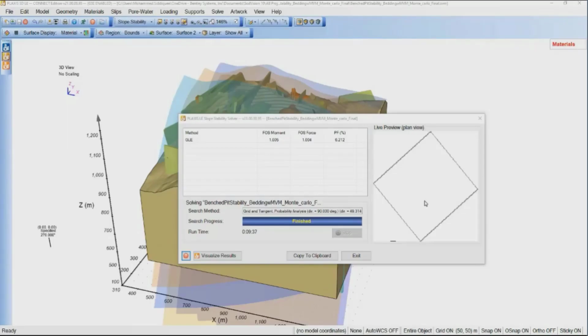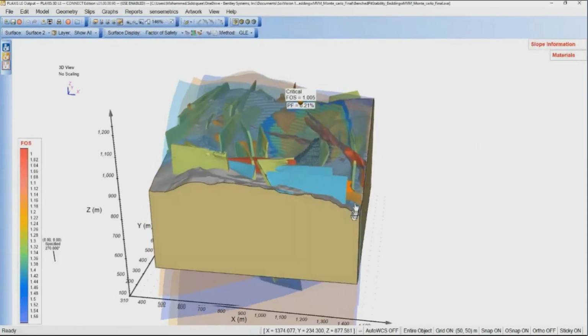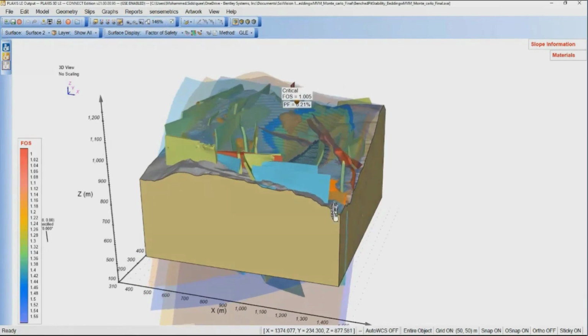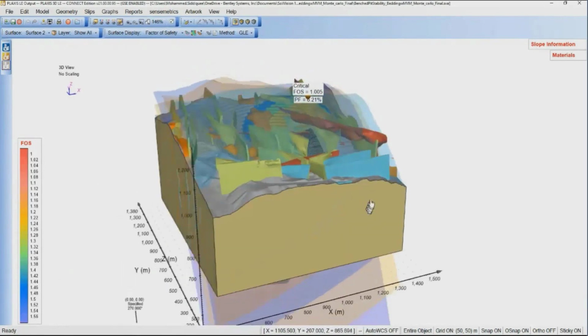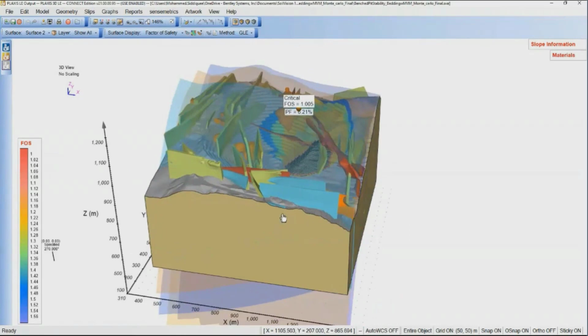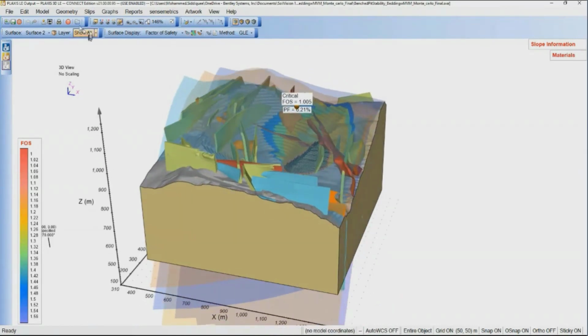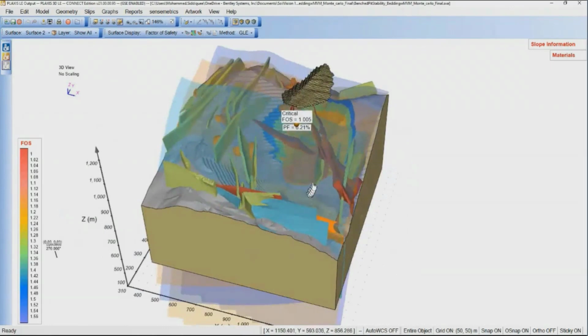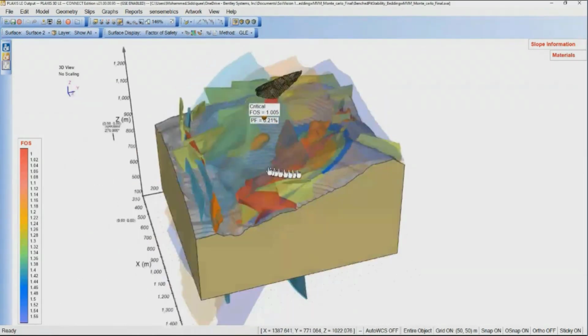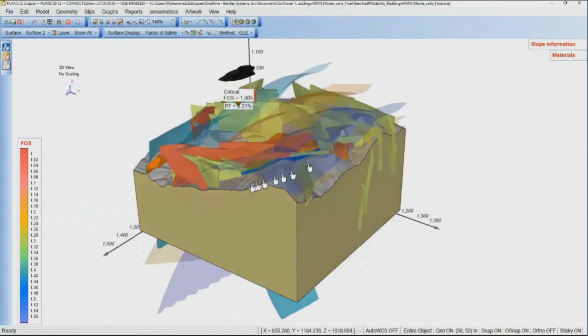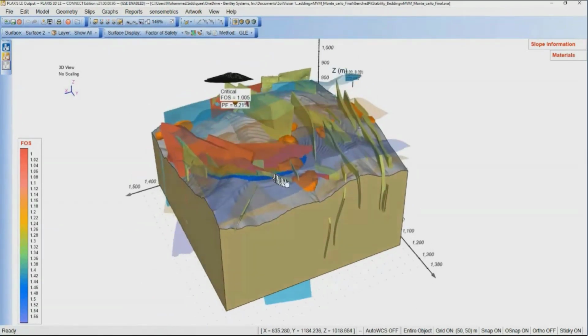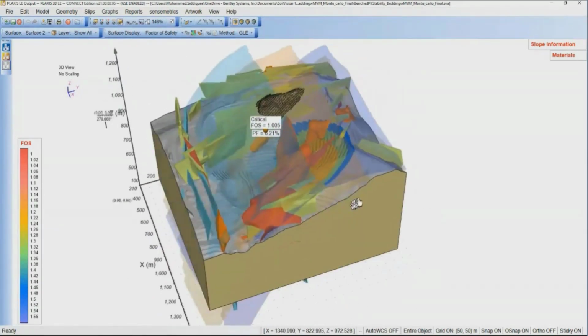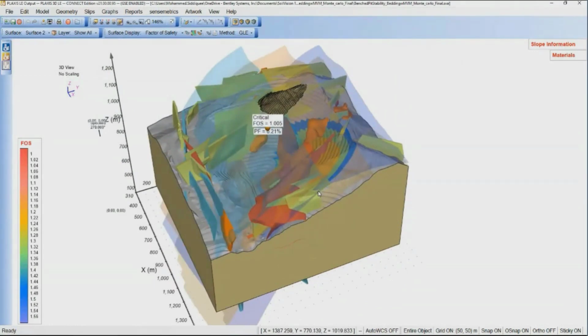So you can see here the run is completed now. So we can see the results. Now this is the failure, so it's a little bit obscured by other planes. Let's blow it up a little bit, so we'll be able to see here. It's pretty nice that you can see that the failure plane is not very ellipsoidal, because it has the weak plane ALM model, so that captured the anisotropic planes as well.